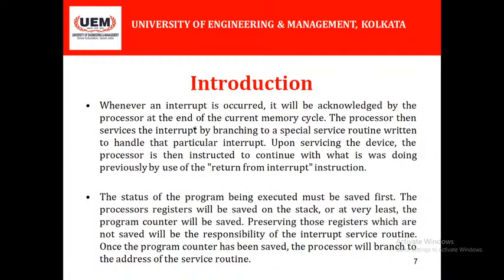Whenever an interrupt occurs, it will be acknowledged by the processor at the end of the current memory cycle. That means, first of all, the current instruction which is being executed by the processor has to be entertained.